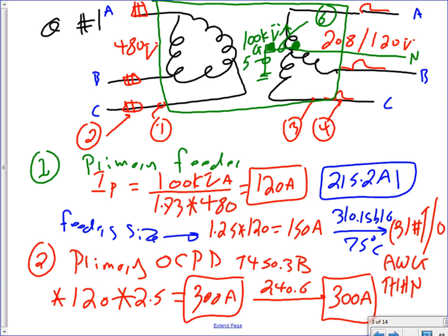Why? What's the disadvantage of going lower? If you go lower, you're taking a risk that every time your transformer starts, you're tripping or burning the fuses. Now, if you're a company like Parsons and Eagan, and you have done tons of them, and you know for a fact this type of transformer works with this type of fuse, and the manufacturer recommended 300, but I know I can put 200 and work with it for 15 projects that we've done. Can I put 200 there? Yes, no problem. The max is 300.